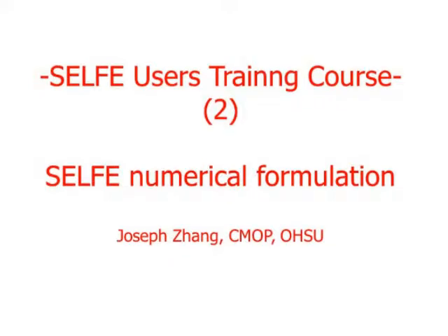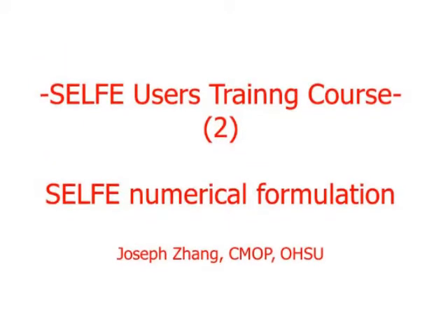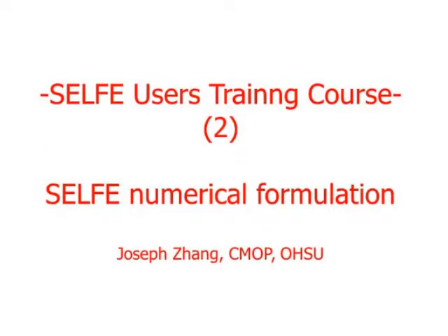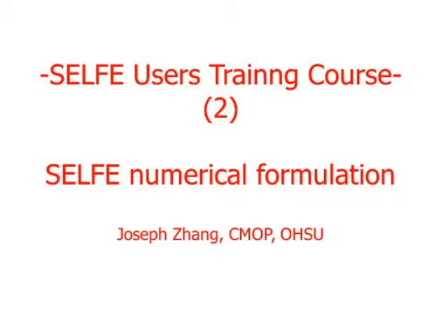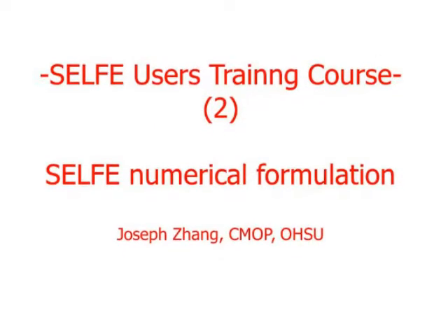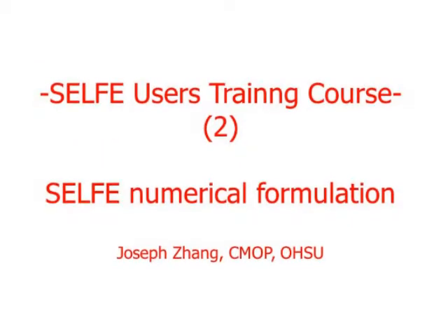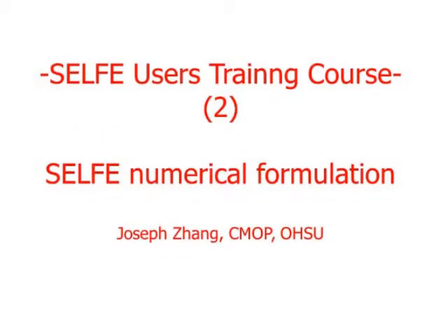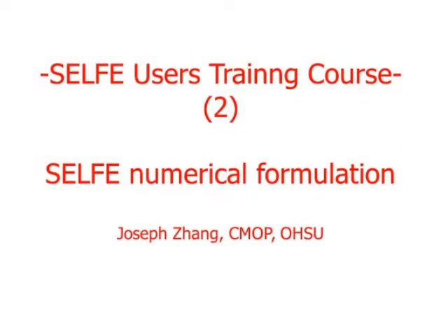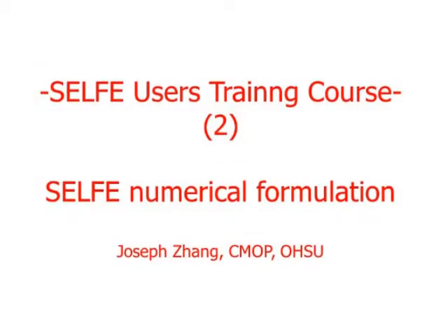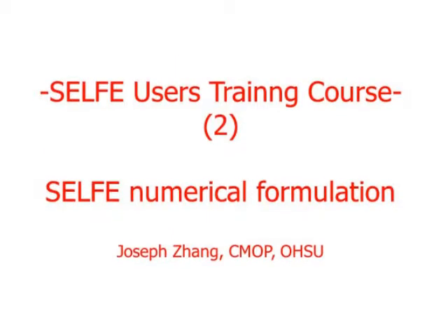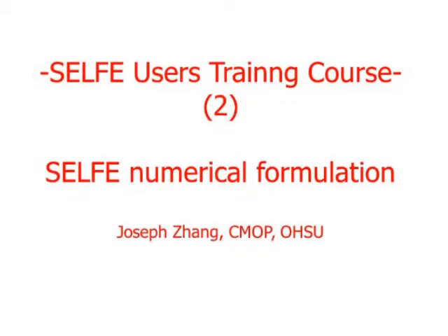And there are many types of finite element methods. Some popular ones include the Galerkin finite element method. In this case, the weighting function is chosen to be the same as the shape function. I will talk about shape functions in the next slide. And if you use least squares, then you minimize this residual here. It's the inner product between the residual and itself, so the weighting function is the residual itself. You basically minimize epsilon squared.